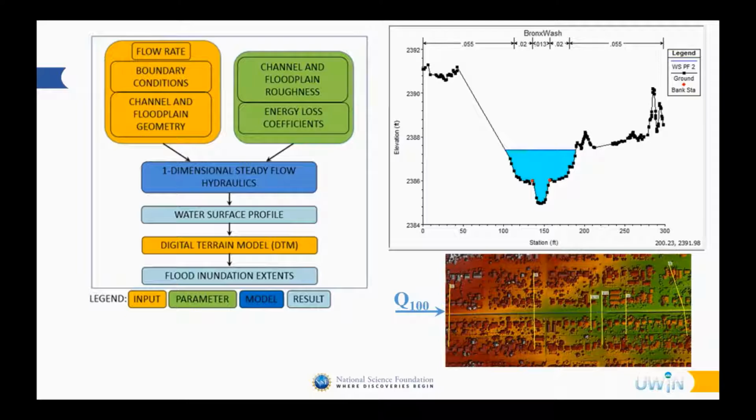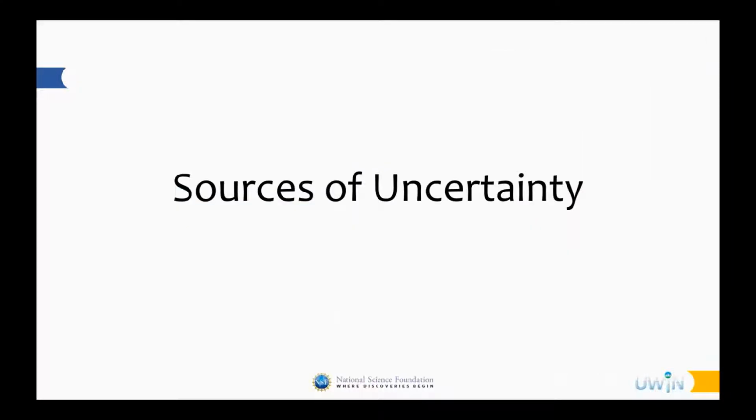So I think you can see across the input data, the parameter specification, the model specification, and so on, there's propagating errors that can add up. And so the panels on the right just depict a one-dimensional floodplain analysis in HEC-RAS where a steady 100-year discharge is imposed on the topography to yield a deterministic floodplain boundary, either you're in or you're out.